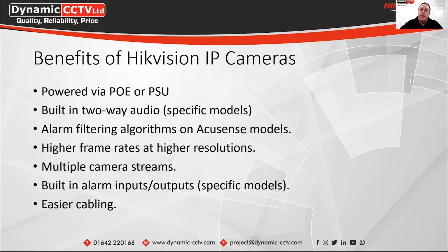With IP systems, you can actually add that IP camera to 2 NVRs at the same time. So long as they're connected to the same network, you can just add the camera to both NVRs, so long as you ensure that the time and date is set exactly the same on both NVRs. If it's different, then you could get an issue where the times jump on the camera's OSD display. Which makes it a lot easier than with TVI recorders, where you have to physically wire everything back to one recorder and then physically wire it to another recorder.